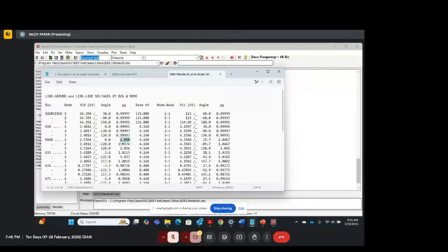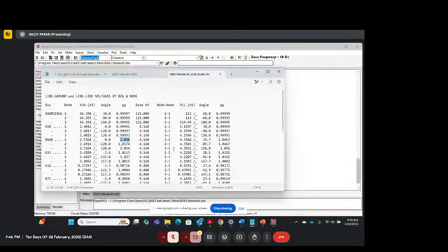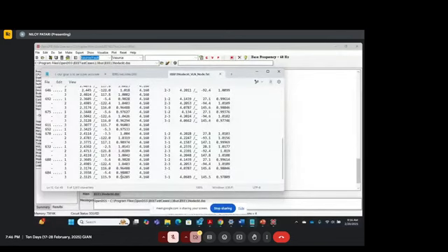This boost was coming off because the regulator had a tap, right? It means the tap settings are kept in such a way that it boosts the voltage. Because this voltage has been boosted up on the substation side, if you see the periphery ends, the periphery end voltages are just above 0.95.